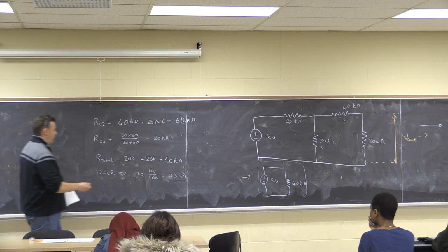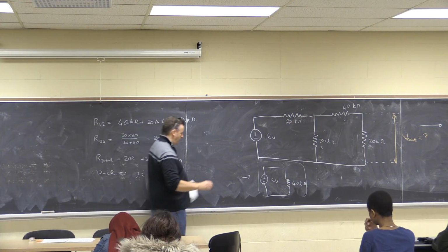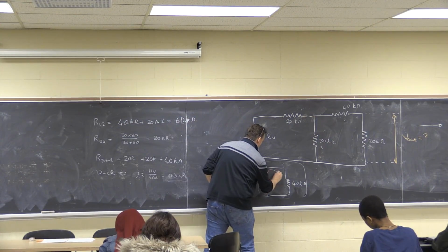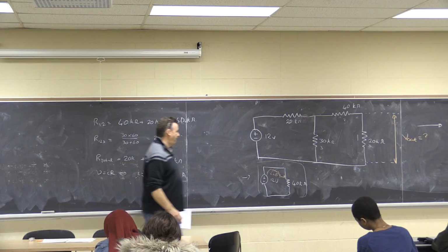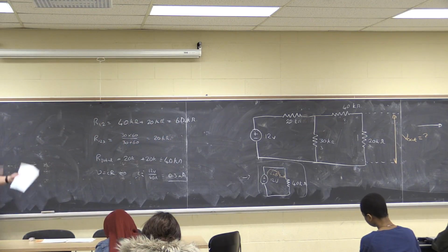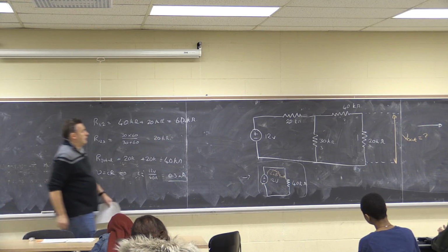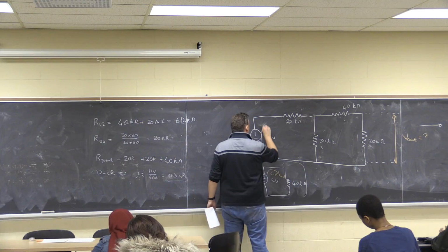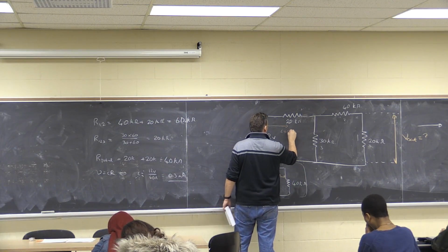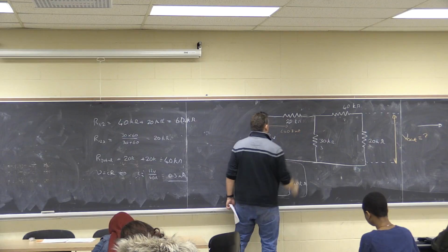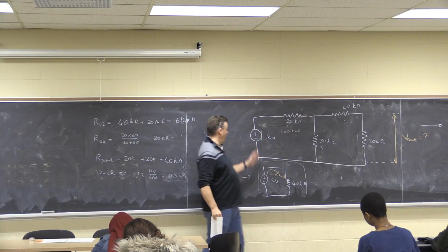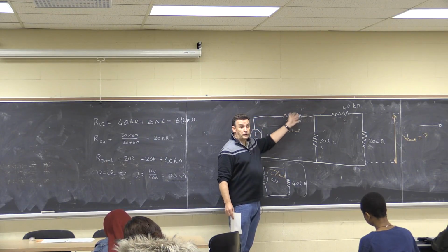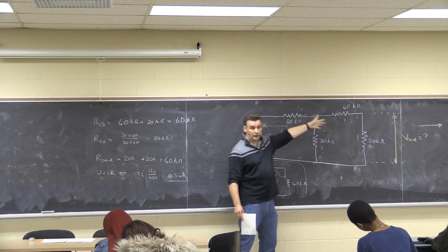So I know the current is 0.3 milliamps. That's the current flowing around this circuit. I equals 0.3 milliamps. Now I have to walk back through the problem. This is where voltage division and current division might help us. The current flowing through here, I, is also 0.3 milliamps. Okay, so the current leaving the source is 0.3 milliamps. Current going through this resistor must also be 0.3. I don't know what happens over here yet.